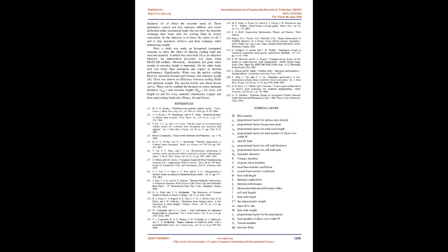The purpose of this section is to introduce design charts that help optimizing hexagonal structures. These charts can improve selection of hexagonal structure main dimensions. Based on cell size, a designer can select optimum wall thickness and structure height. Hence, he would be able to maximize both mechanical and thermal performances of the structure.